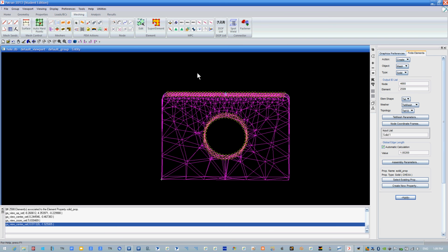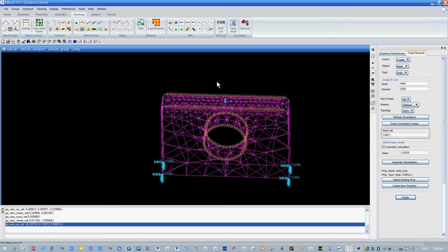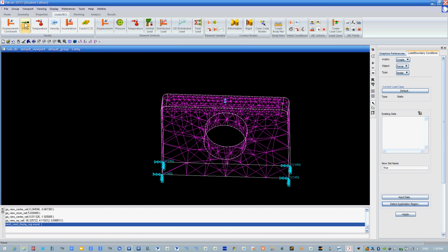The thing is, you want your mesh made before you go to apply your force, because you're going to apply that force to an FEM region. And that's important, because if you apply it to the point we made earlier, it's not going to register, you're going to get 0 deformation, 0 forces, and it's not going to work.